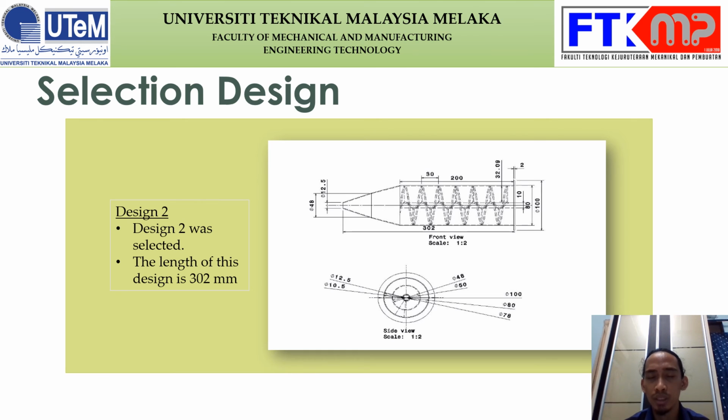The reason I chose it is that the longer the spiral channel, the more advantage it gives to the pouring process, because we want the dendritic structure to be cut off speedily before getting into the mold.